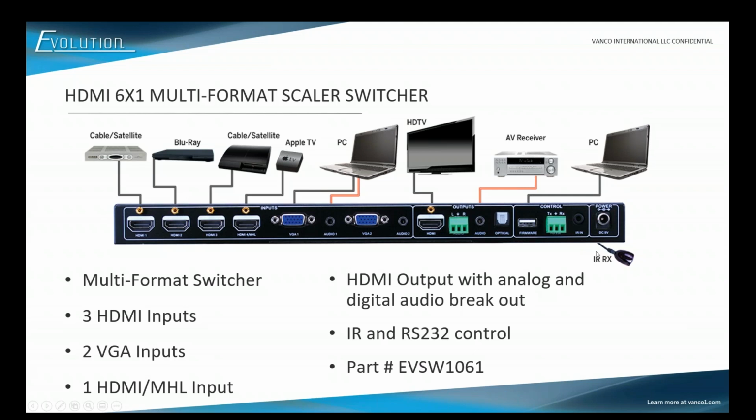So where would you use this? Conference room type setup. In fact, we used to use this piece in our conference room before we switched over to HDMI over IP. It was a great little unit because if someone comes in, it doesn't matter if they have an older computer with VGA or a newer computer with HDMI, they can plug right in. And obviously, if they're utilizing HDMI, it just passes through. If they're utilizing VGA, it upconverts or upscales the resolution to HDMI. So great little piece for conference rooms.